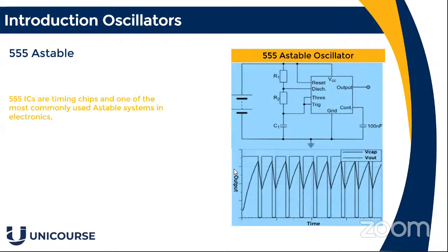So now we've got this astable circuit. This is using the 555. We've got 2 waveforms here, and the reason I have 2 waveforms is that it depends on which part of the output you look at. So you've got the output over here, which will give you a nice clean square wave. If you don't get a clean square wave, then you've got something wrong with your circuit, or the chip's not in properly, or you haven't got the right grounding.